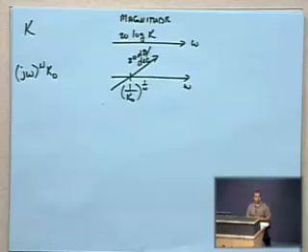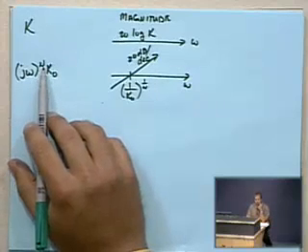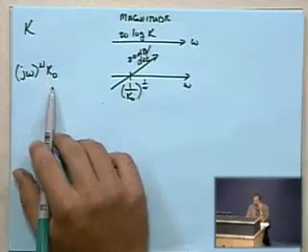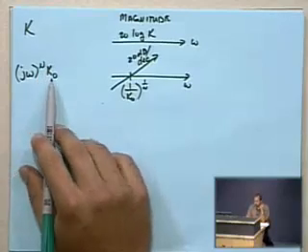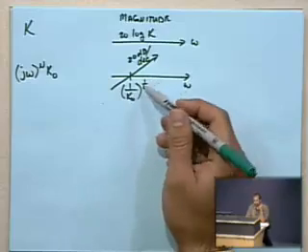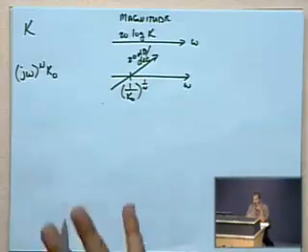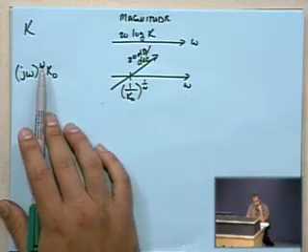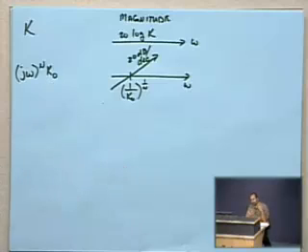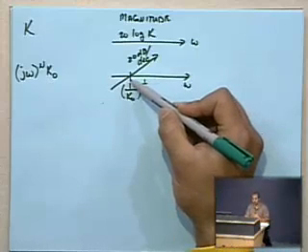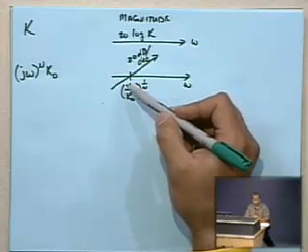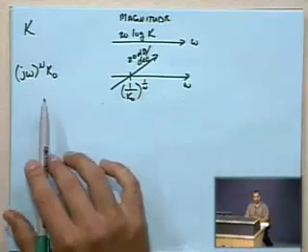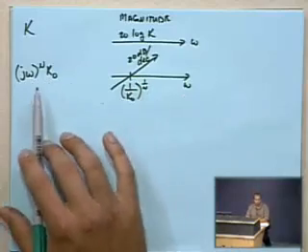And so for a simple case, if n happens to be 1, for example, and k0 happens to be 1, then when you plug that in over here, you have 1 over 1 to the 1 over 1th power. So if you have a j omega term of degree 1, and there is no k0 term specifically, then it's going to be a 20 dB per decade linearly increasing function that crosses the x-axis at 1. But this is the most general form of this equation, or general form of the situation.